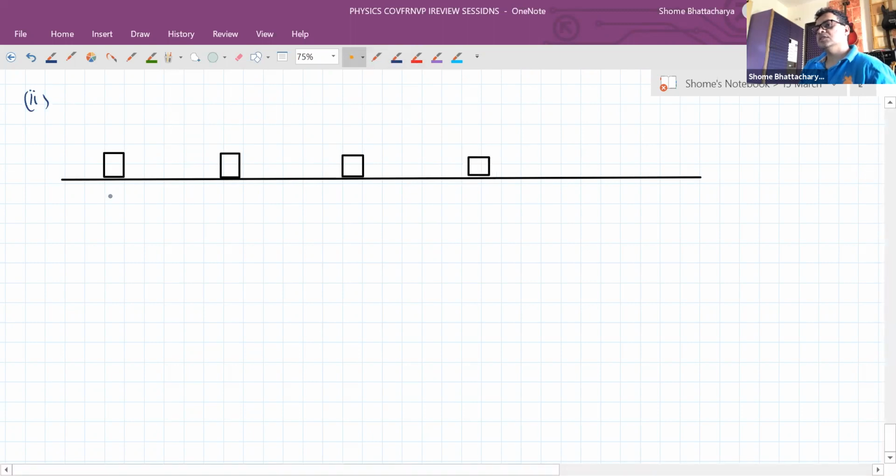Okay, so this is, let's say, at t equal to 0, u is 0, but we start applying the external force of 30 newtons. Immediately there is kinetic friction that acts of 20 newtons that we have seen earlier. So it has an acceleration of 1 meter per second square.